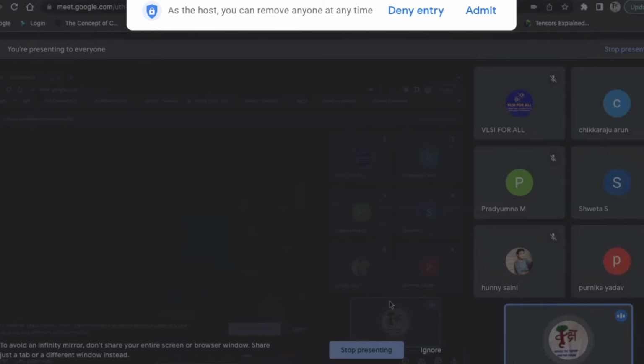Also, functional verification is related to, like, we have a design, and the design is consuming X watt of power, and we want this design to consume less power than X watt. So we do the verification to find the certain points because of which we are getting this much power. So this is one more thread of functional verification. Okay, but doing testing with some DFT architectures and the test generation process is divided into this ideal testing and real testing. Okay.